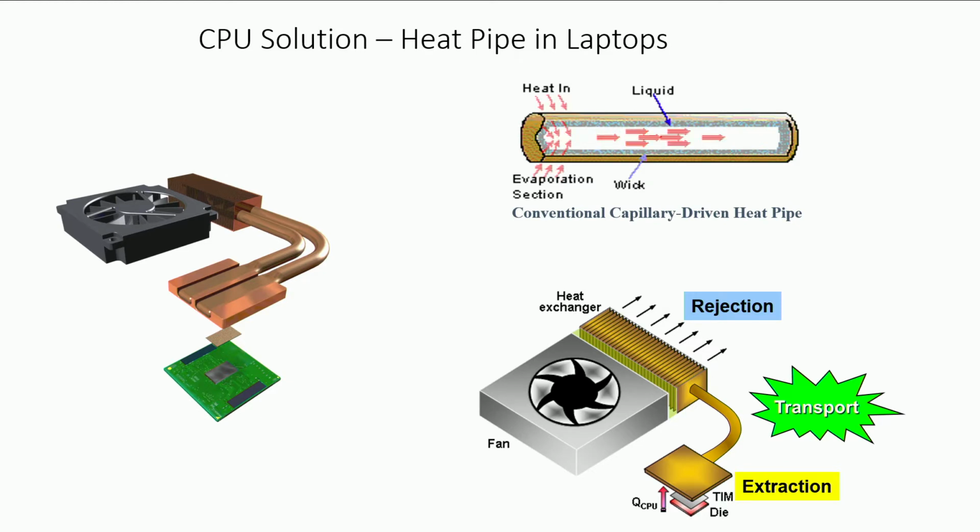Now if you do this momentum balance and work out everything to get the flow rate, it can be shown, as a thumb rule that is followed quite regularly, that for a straight heat pipe the heat carrying capacity, the maximum heat that you can transport, is inversely proportional to the length through which it has to travel. Because each of these pressure drops is a function of length. And if you have bends, they all add up.